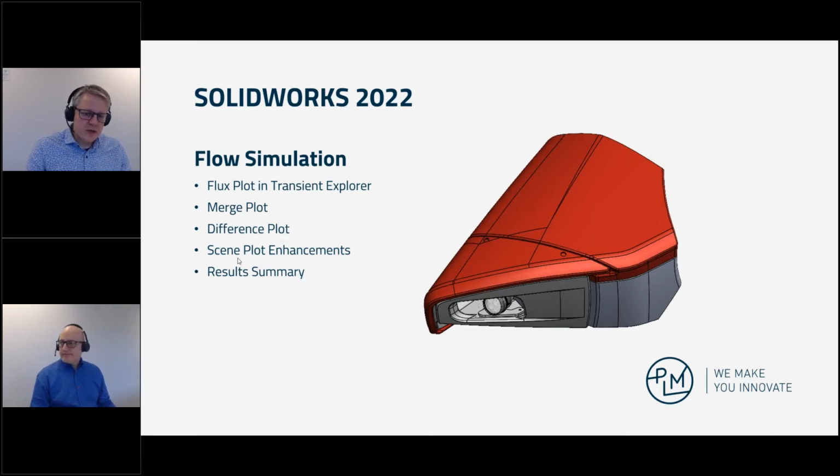Scene plot enhancement means that the view of the model, how it's positioned during the analysis, is now saved within the model. So you will see the same results as you see on the screen when you analyze it, and it remembers it. It really stores the model orientation, its zoom, the parts' visibility and so on.